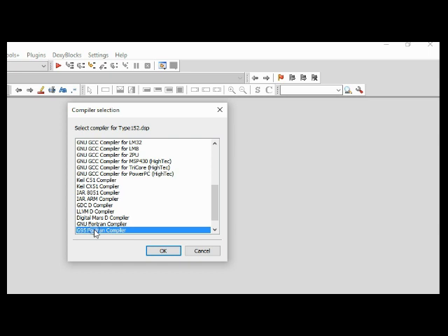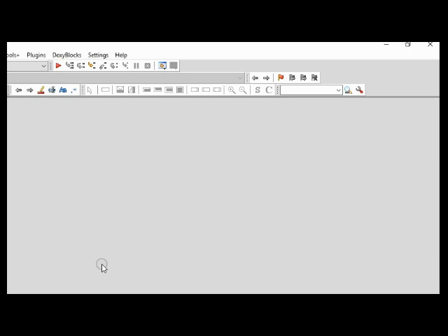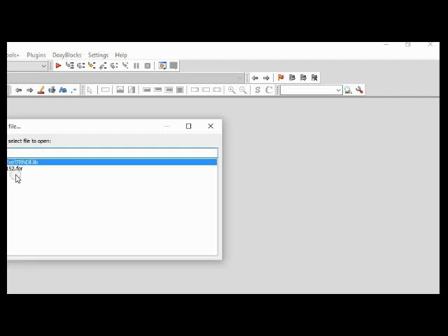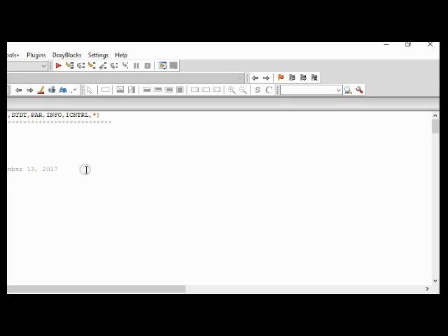Alright, this is my Code::Blocks integrated development environment open, and then compiler selection. You can see Code::Blocks has many other compilers installed within it, but we are concerned with the G95 Fortran compiler, which is compatible with Trnsys. The rest are not, and we click OK.